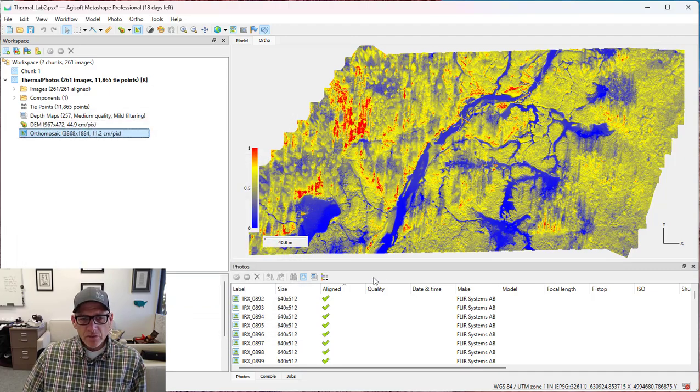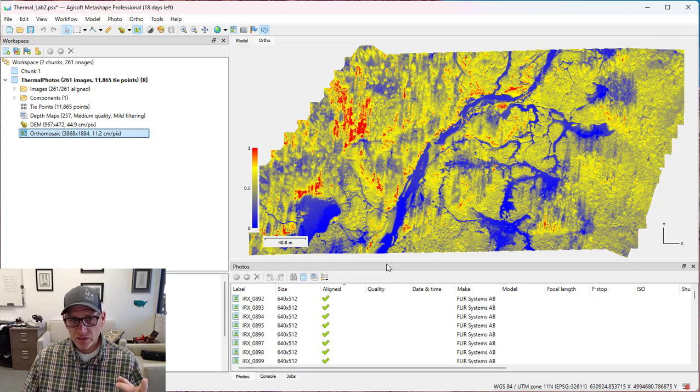Okay. Now the other interesting thing to note is once we've applied the color ramp, first of all, we're looking at the actual temperature values now, not the RGB representation of it. But second, as I move my mouse over this area, check out down here in the bottom right-hand corner, this index value.